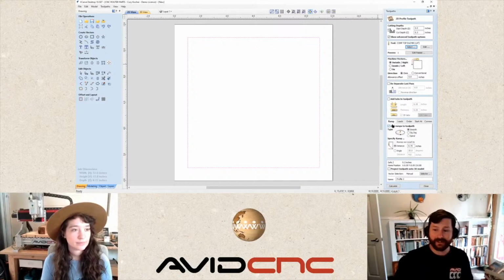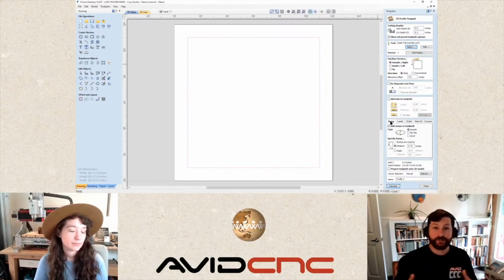and a lead. And that is because end mills are not great drills. They don't go straight down into our material well. They need lateral movement to evacuate the chips. And so we want to make sure that we're giving that tool that lateral movement, because at the end of the day, that's giving us more tool life, which means the tool is more cost effective.